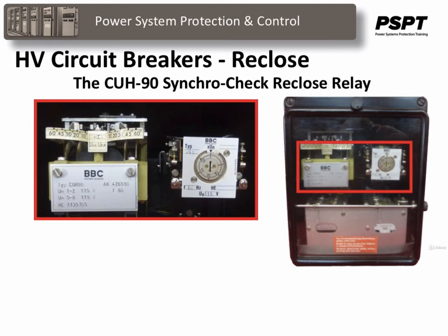In the case of high voltage circuit breaker reclosures, the protection for, say, line protection will immediately, upon tripping, at the same time initiate an automatic reclose feature, which can be selected or deselected by the operator when operating the station, either remotely or on site. The reclose relays themselves that provide the reclosing function are associated with a breaker, and there may be 2 or 3 breakers associated with the tripping of a line.